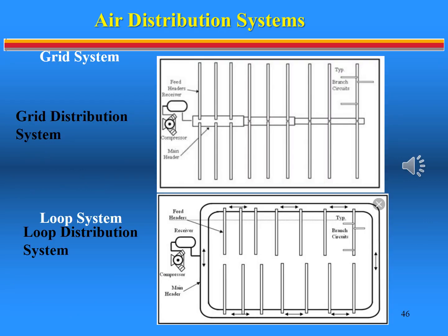Two of the most common air delivery systems used are grid and loop. The grid system is easy to install and often is selected when an existing facility is being utilized for compressed air operations. The chief disadvantage with the grid system is that long piping can cause pressure drops under heavy demand. Looping the piping has two effects. It equalizes the pressure drop because now the critical end use has at least two more diverse parallel paths to receive compressed air. And having a loop typically means the piping is the same size throughout the loop rather than reducing the size near the end.